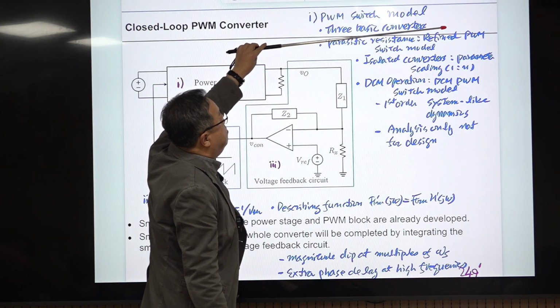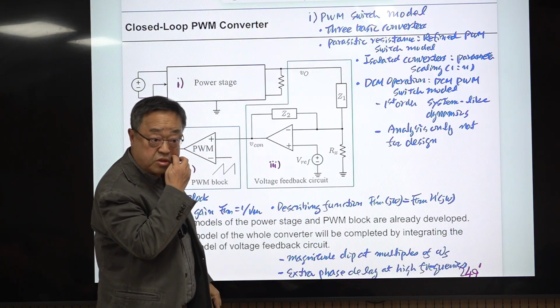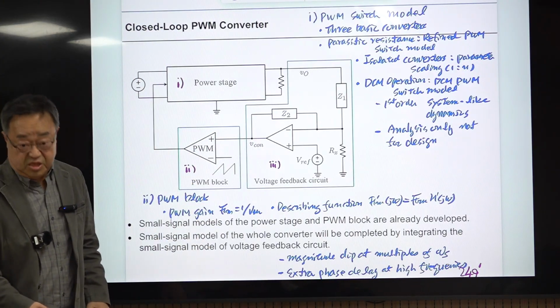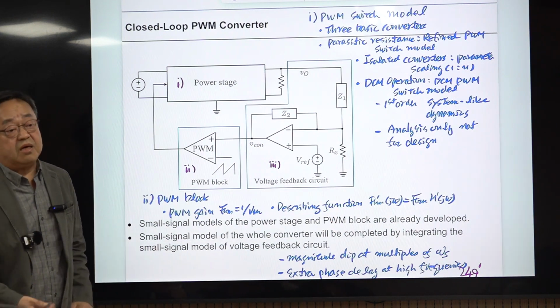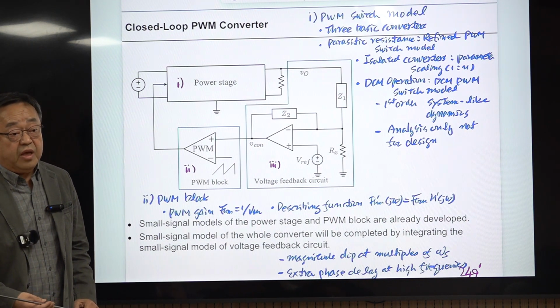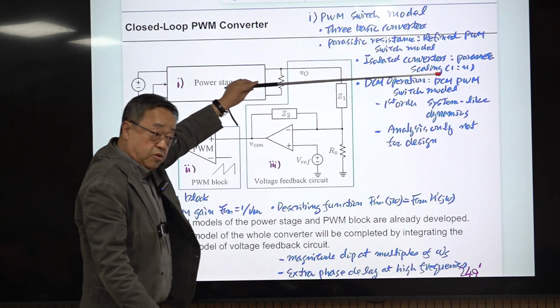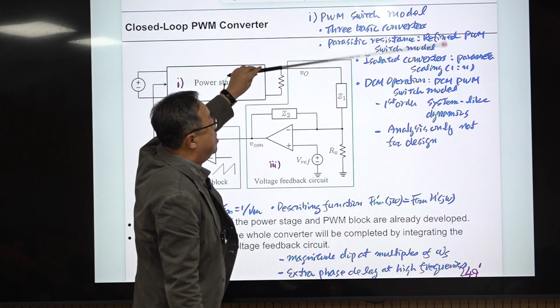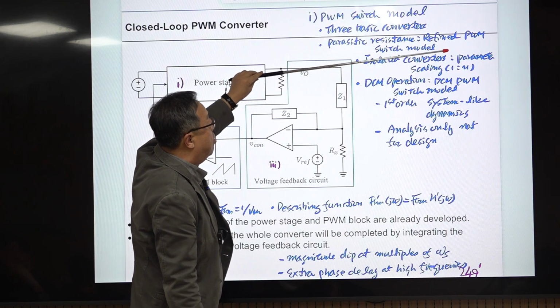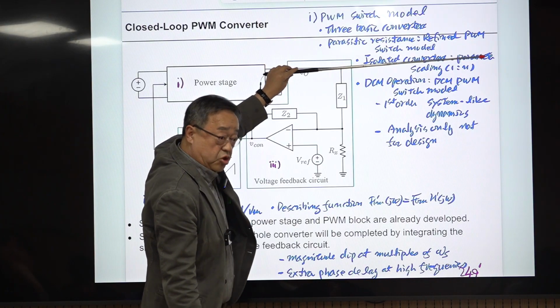The simplified PWM switch model can be applied to all the PWM converters, even with the parasitic resistance. Okay, there is not much difference between exact model prediction and simplified model prediction. But you should know this. Okay, so when you have a chance to simulate this PWM switch or PWM converter, it's better to use this refined PWM switch model.